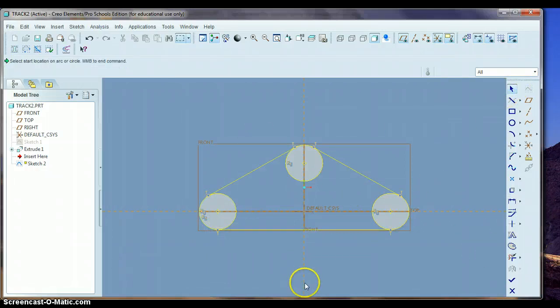Okay, now we're going to use the delete segment tool, which is the 4th button from the bottom. It's got this little red squiggly line in a blue corner. If you hover your mouse over it, it says delete segment. If you click on that, get rid of the inside of the circles. We used this button last week. So when you get done, you should just have a line, the outside of the arc, the line, the outside of that. Anything else on the inside should be deleted. Everybody have that? Need help, Ben?